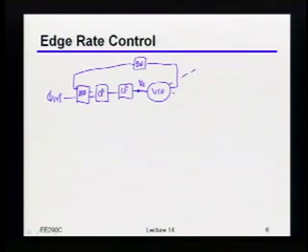And remember, inside of that VCO, there's basically just a bunch of inverters, right? Where that control voltage usually ends up controlling the power supply, okay? So in other words, if I know that I'm running at, let's say, 1 gigahertz, that control voltage is automatically going to go to whatever it needs to go to give you inverters that basically, after a certain number of delays, give you a 1 gigahertz clock, right?